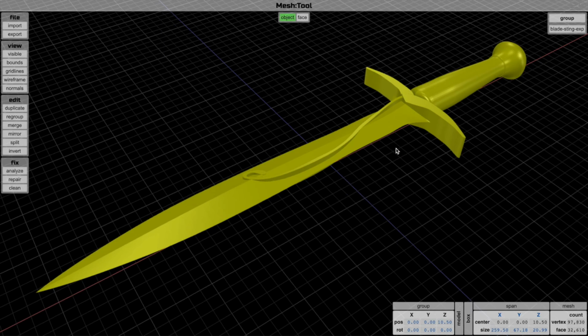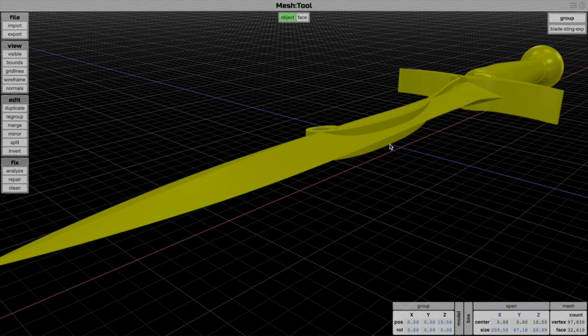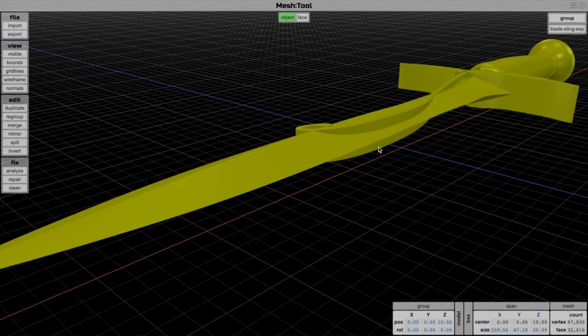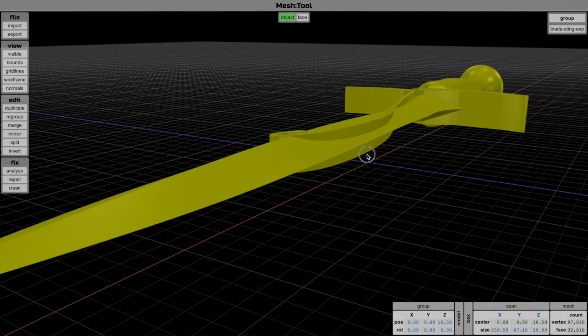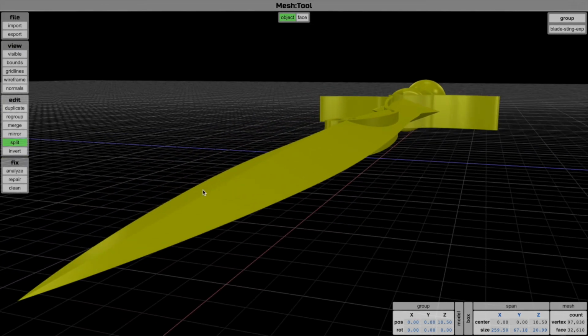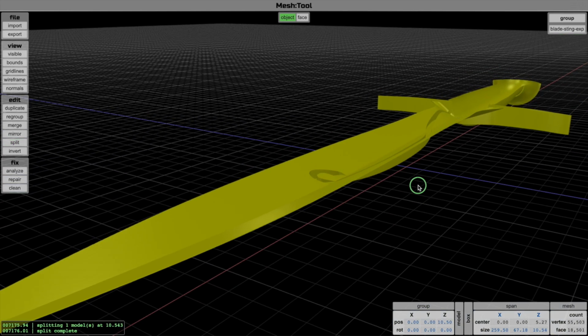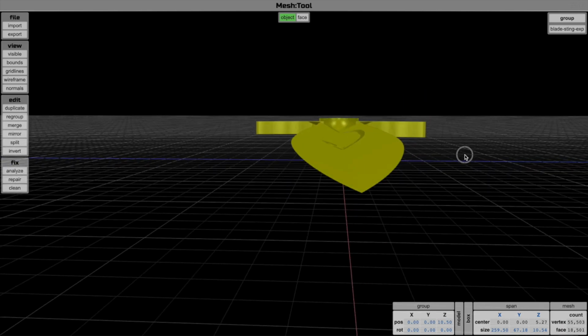And then the last thing I wanted to cover is an extension of the whole idea of splitting and merging and mirroring. So for non-manifold parts, you want to edit the interior, and what we can do here is click on split, split this part down the middle, delete the top, and now we can see sort of the internals of this thing.